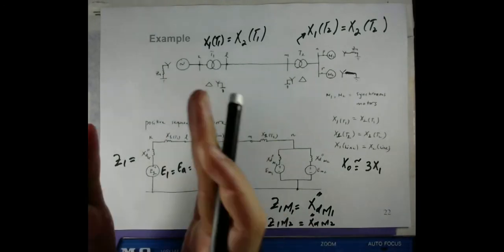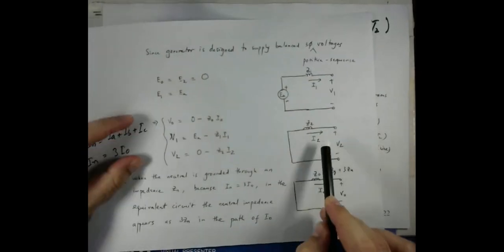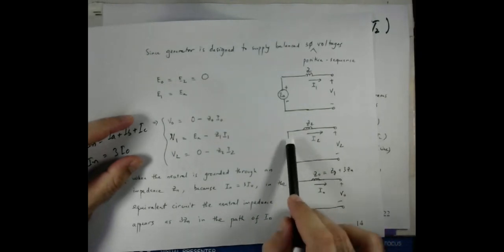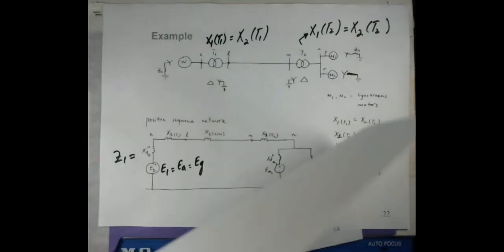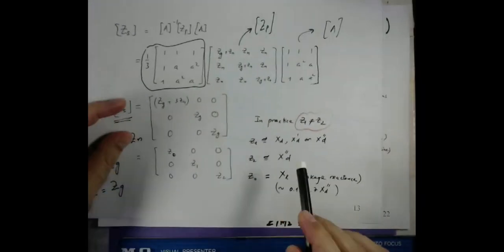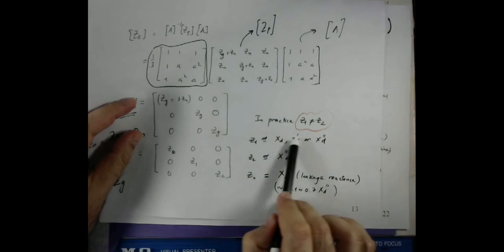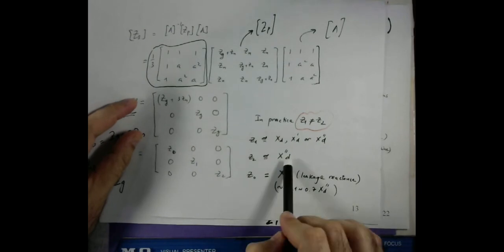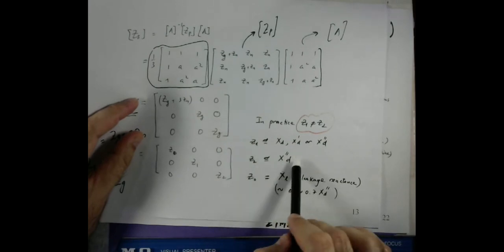networks. So as you know, we discussed that in the case of the negative sequence network for the synchronous machine, there is no voltage source. I mean, neither in the negative sequence network, neither in the zero sequence network. So this is important to consider. Also, another point is that we will still take the negative sequence impedance as the subtransient reactance, because positive sequence impedance can be either of these terms, but the negative sequence impedance is approximately equal to the subtransient inductive reactance. Since we have taken Z1 also as this one, in the negative sequence network it will also be the same term.